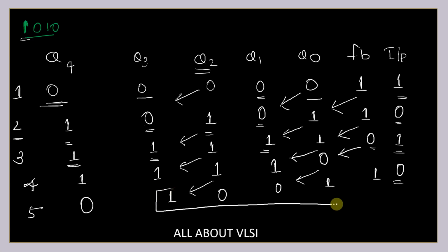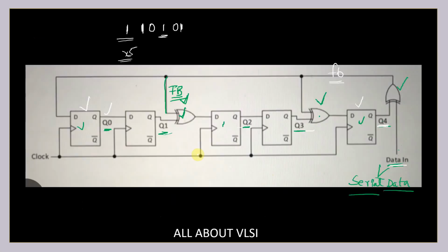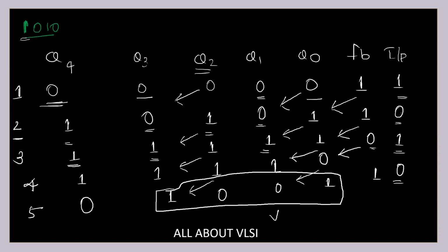So this is the CRC, that is my remainder, which is the appended or redundant bit which I'm going to have. This particular value will be stored inside your register as 1001. And we are going to take it from this register and append it with our original data. Now, this is how we are going to perform the CRC calculation. But if you have carefully observed, we had 4 data items that we need to pass serially, and we need some cycles to get our actual result, which we want to append with our original data. That is my redundant bit.